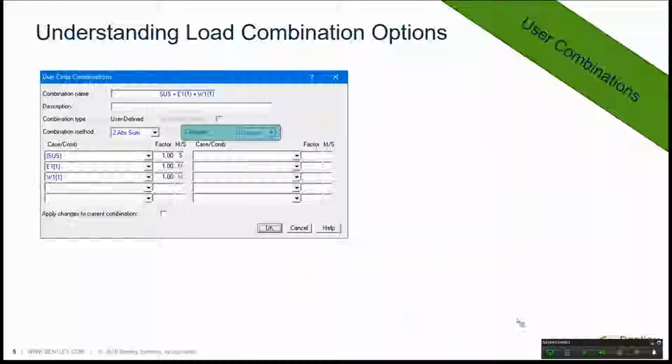Next, specifically if you're creating a code combination, the user must select the stress category under which this code compliance combination will be evaluated. In each of these categories, the calculated value is compared to the allowable code value, and overstressed piping will be marked in the results, either by color coding on the interactive scan or by tagging in the output report.